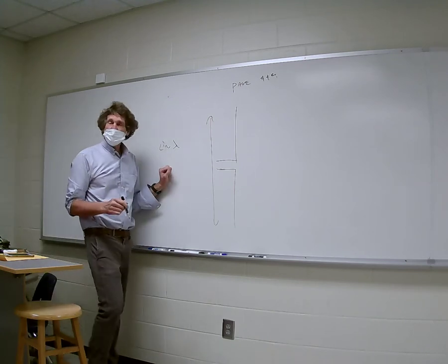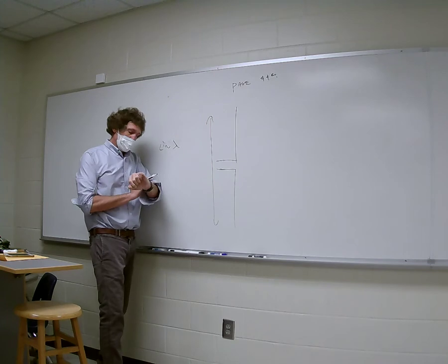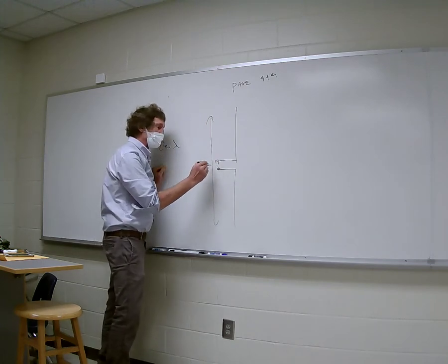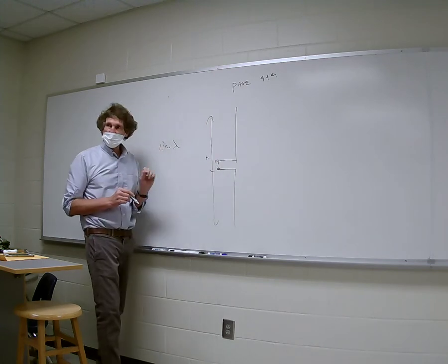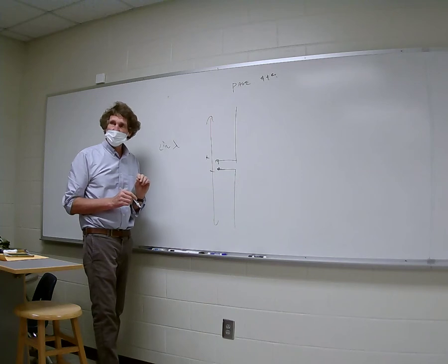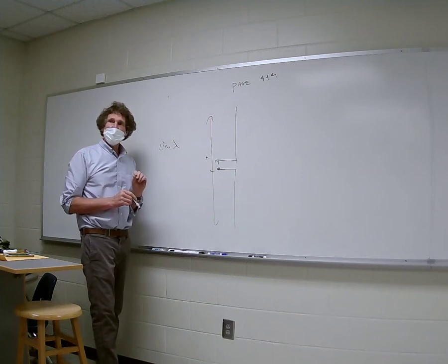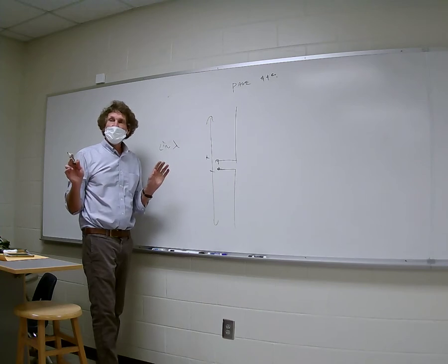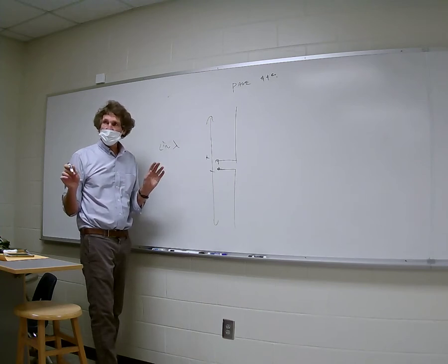When we talk about antennas, another thing, we always assume the voltage feeds them differentially right at the center. They don't have to be fed this way. But if you don't do it that way, you're going to have some behavior that's anomalous, and I don't want to get into it yet. It's center fed, symmetrically fed.